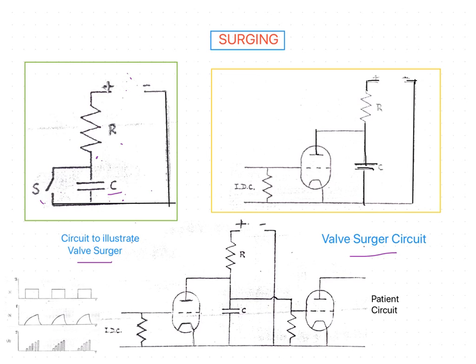As the circuit contains a resistance, the charging is fairly slow. The potential difference between the plates rises quickly at first, then more slowly, as the potential difference developed opposes the charging current.